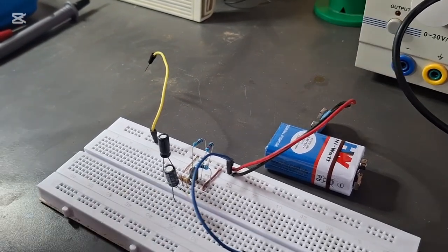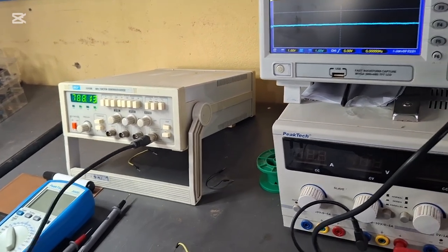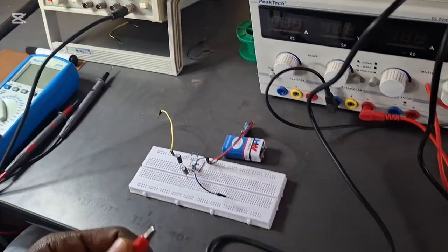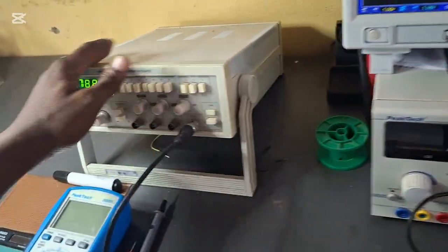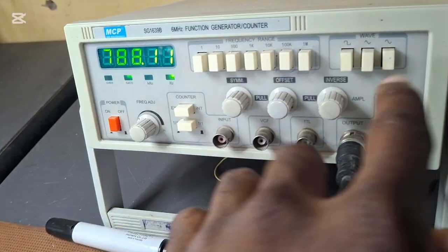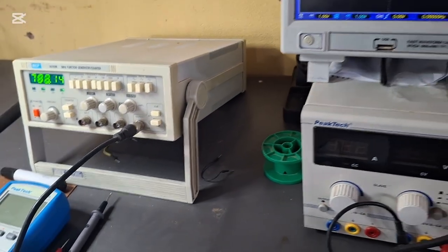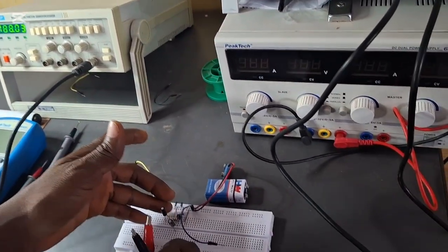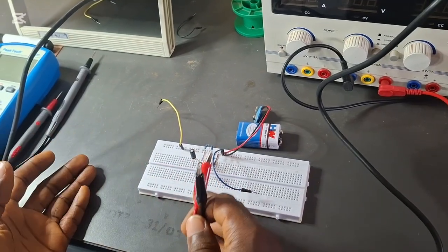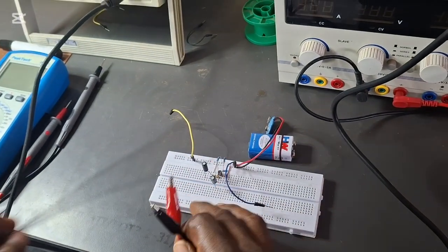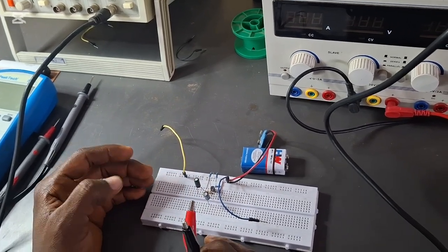coupling capacitors is that we are going to look at the AC analysis, where we'll be feeding an AC signal, or let's say a sinusoidal signal, from the function generator here. This is a function generator. So we'll be feeding a sine wave into the amplifier, and we don't want the DC voltage that is used to power the transistor amplifier to interfere with the AC signal. So that is the reason why we have the capacitors installed.